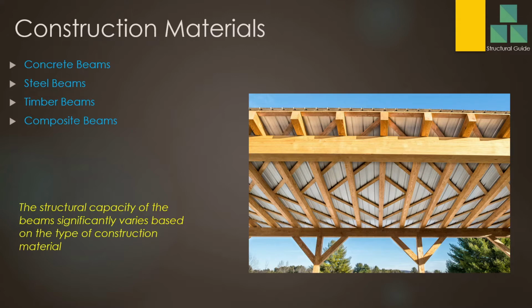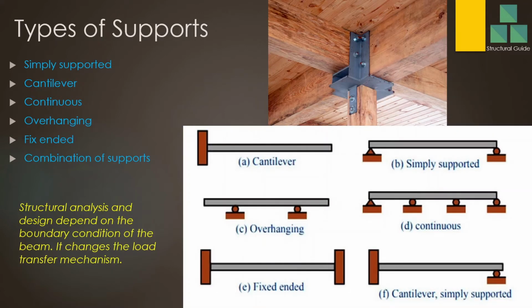In addition, in retrofitting we also use these composite beams. Now, if we have a concrete beam and it has some sort of issues, we may fix side plates or a bottom plate. We fix the plate to increase the stiffness of the beam. In such situations, those beams also can be considered as composite beams. So let's discuss the other method of classification of beams.